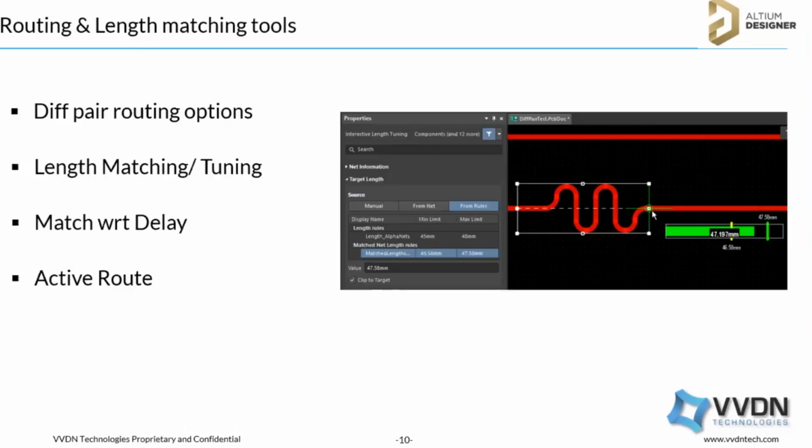So this active route, you are able to define the layer, the signal in the routing path, as well as the layers, and you can also enable automatic tuning. Based on the constraints, it takes the track width, clearance, and the tuning, matching, length match target. So it automatically completes the routing based on the flow, how you have defined.